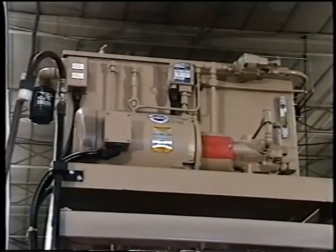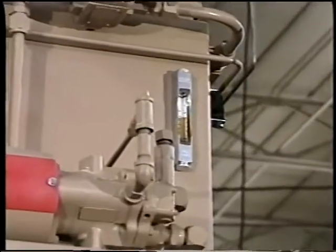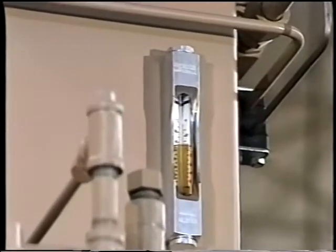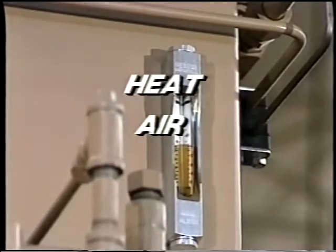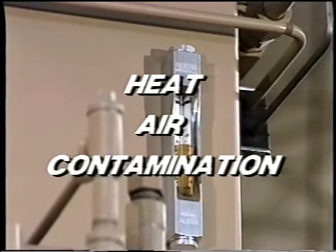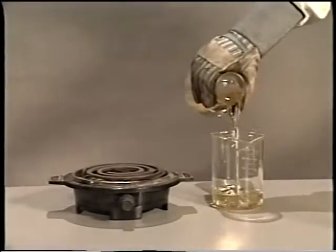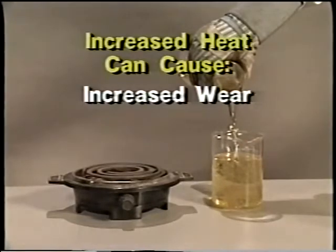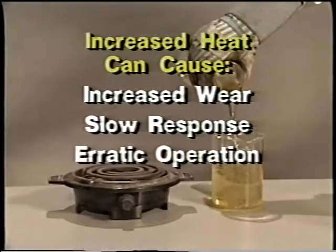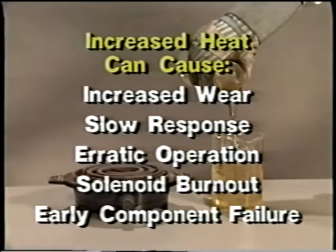How efficiently a hydraulic system operates and how long various components last depends a great deal on the condition of the fluid in the system. Excessive heat, entrained air, and contamination can all affect the overall performance of the system. If the fluid gets too hot, it will lose viscosity and may not provide adequate lubrication. This can lead to increased wear, slow response, erratic operation, solenoid burnout, and early component failure.